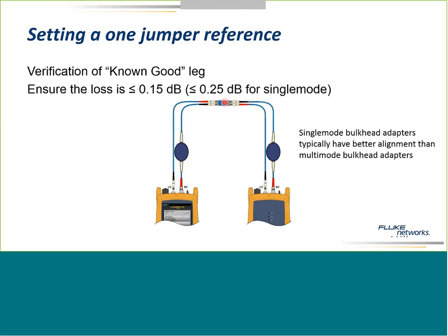One of the things that's neat about testing this known good leg, a simple rule for you guys when you're in the field, another question I get a lot is, how often should I be resetting my reference? Well, you have to set a reference every 24 hours with the Certifiber platform. And we used to suggest that every time you turn the tester off, you should reset the reference. It gets to be a little tedious. You go to lunch, you come back from lunch, the tester powered down. Do I really have to set a reference?